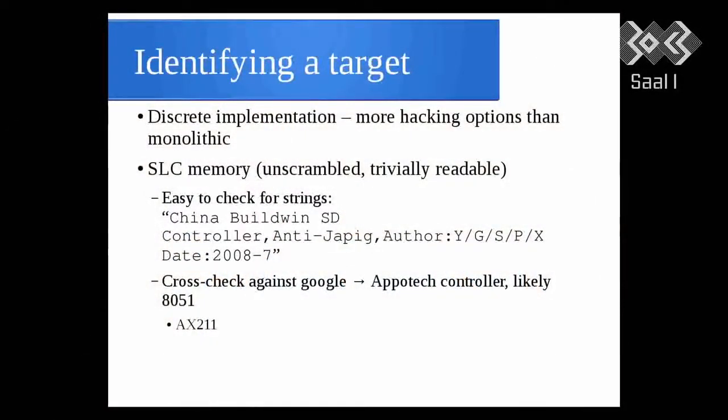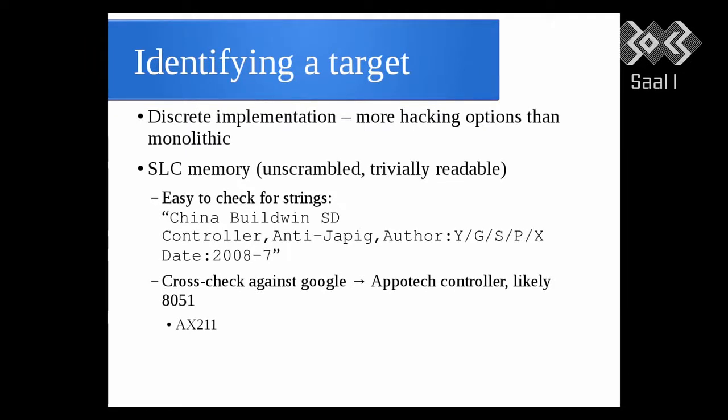We took a look around first thing and found this string on the inside, China Buildwin SD controller. Go into Google, plug in a little bit, come out, okay, there's a company called Apotec that makes this, likely an 8051, we figured probably the AX211 microcontroller.